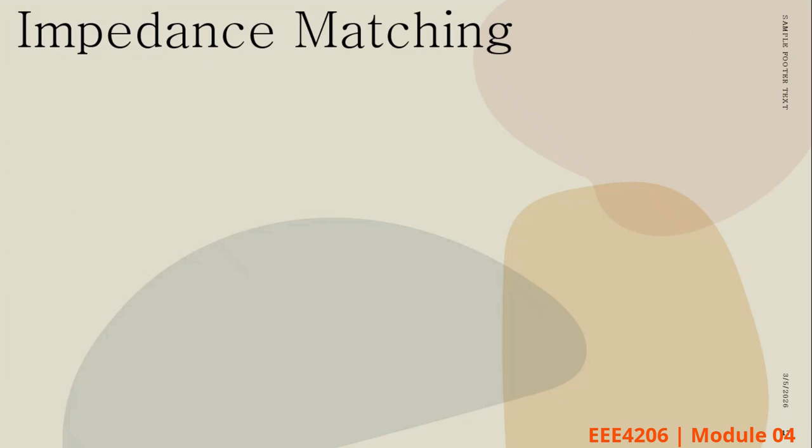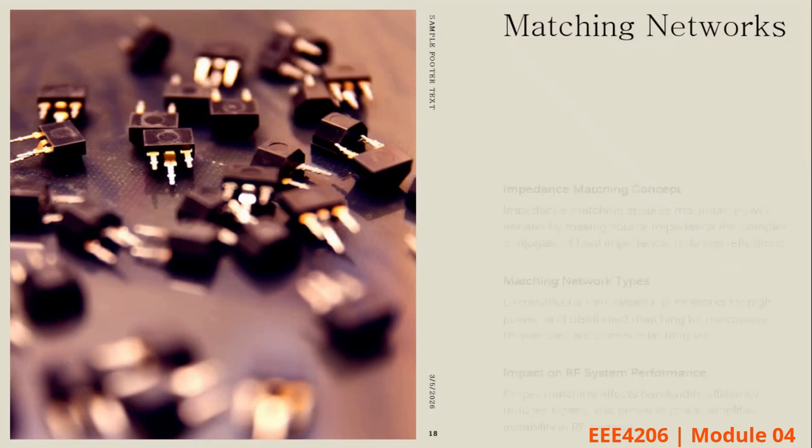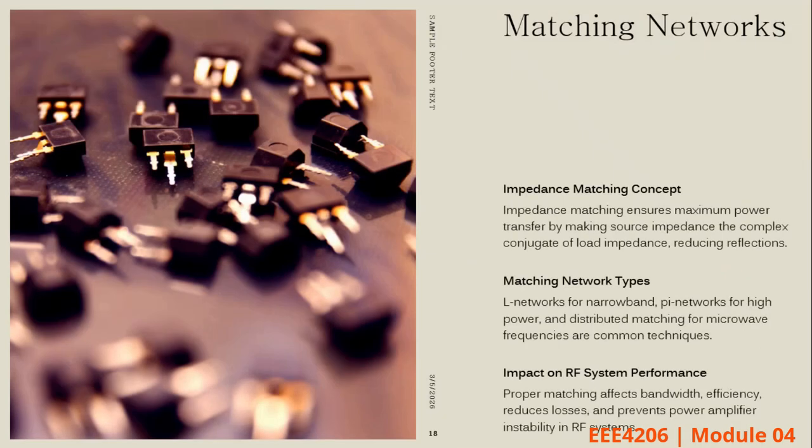Okay, so let's look at impedance matching. I think for each and every lecture we have talked about this, and by this time you understand what impedance matching means. And you also have different techniques of how you do the matching, and you've done some computations. Okay, and in RF systems, you need to talk about matching. So impedance matching is absolutely essential, and you can't avoid it. So maximum power transfer occurs when the load impedance is the complex conjugate of the source impedance.